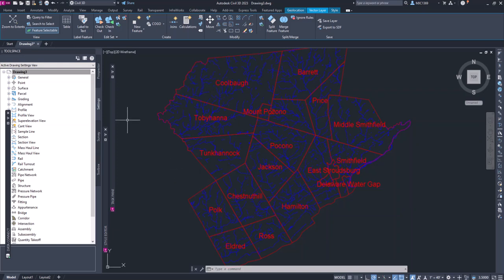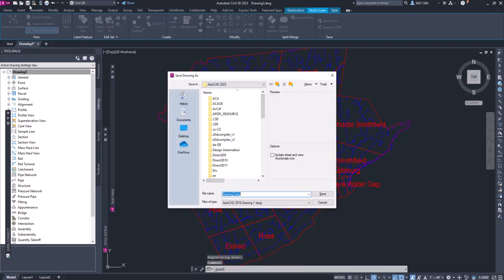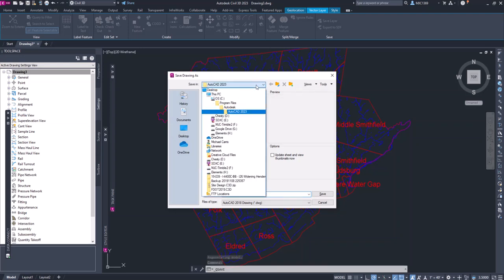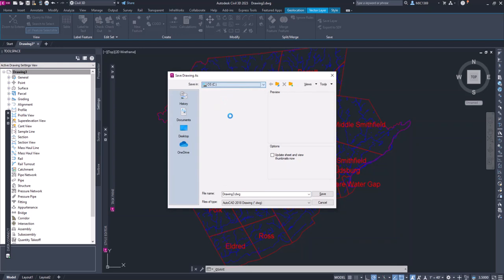It's probably a good time to save the drawing. Let's click on save, the disk at the very top. We can save this in our project folder that we're working in. You can go right to the Civil 3D Design, under Site Design. You can put it under Working with GIS Data. And in here we can name it water and muni BNDY. Go ahead and click save.